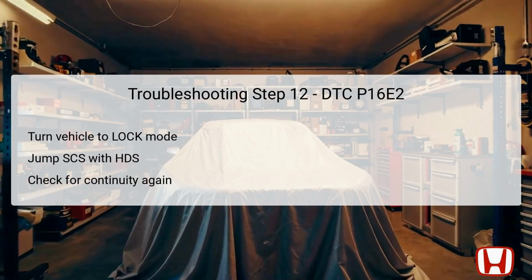Following this, disconnect the alternator 1P and PCM connector B, 51P, to perform a final continuity test between the alternator's female terminal number 1 and PCM connector B's number 40. If this test shows continuity, it affirms that the LIN wiring remains functional. However, if there is no continuity, the diagnosis directs focus on repairing the open circuit in the LIN wire running between the PCM and the alternator, ensuring that the communication channel is restored and functioning effectively.